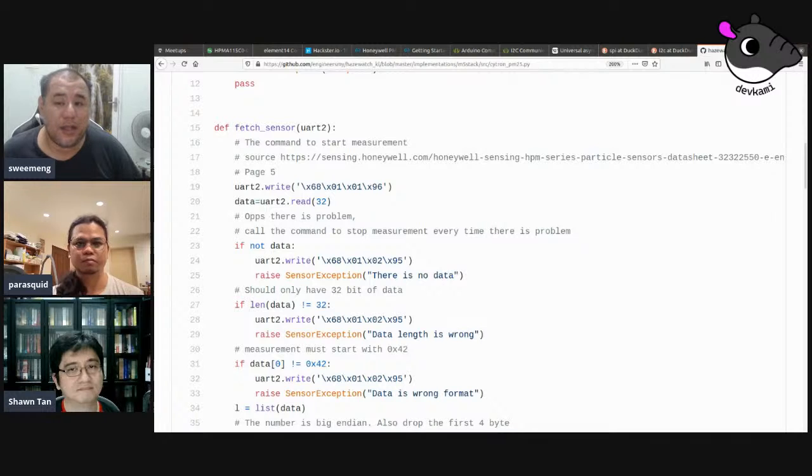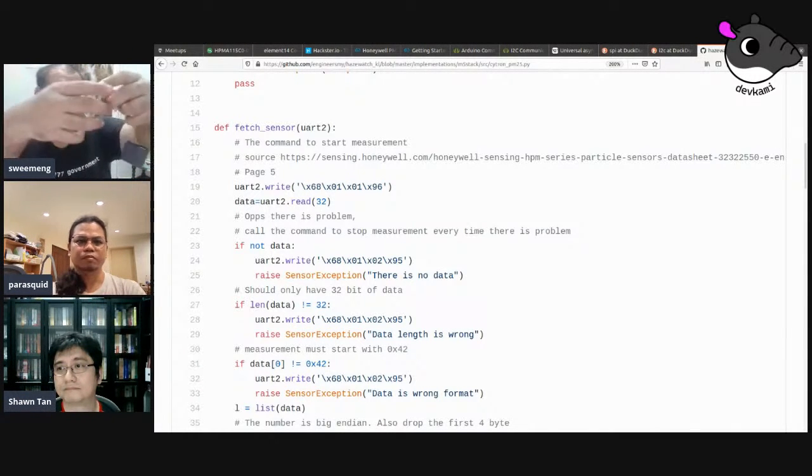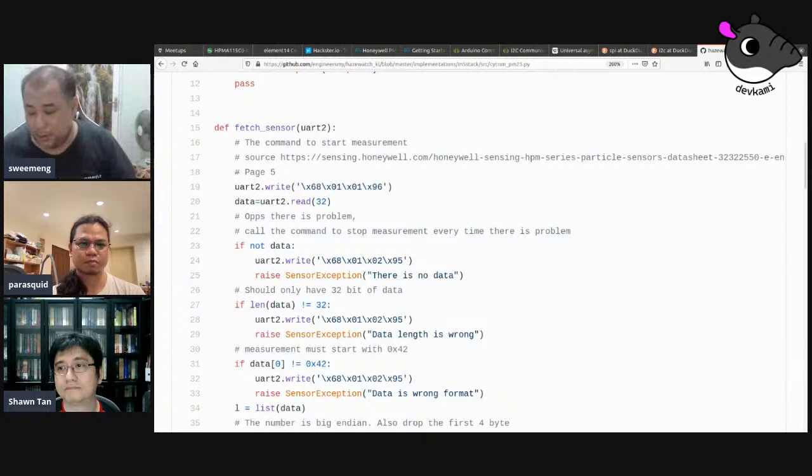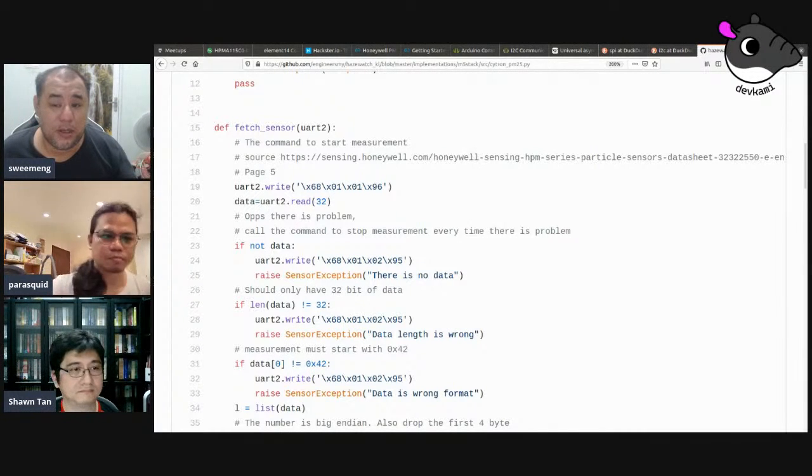UART is a more understandable protocol, because this is what we use with Arduino when we do debugging. We actually use serial communication to debug, and sometimes I use it machine to machine. So for example, again, my favorite sensor, this guy outputs UART through this connector. Then also, I think we covered the 3 one. Anything else you want to add before I go on?